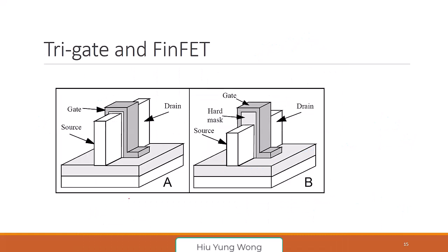So naturally, if you think 2 is good, you'll think I want 3, 4, 5, okay? So there are 2 types of gates. We can even do tri-gates. This is the silicon. This looks like what? This is a fin, right? Like the fin of a fish, right? The fish is here at the bottom, the body, and then you have this fin. This is the source and this is the drain. And what we're doing, you just wrap the fin by the gate.